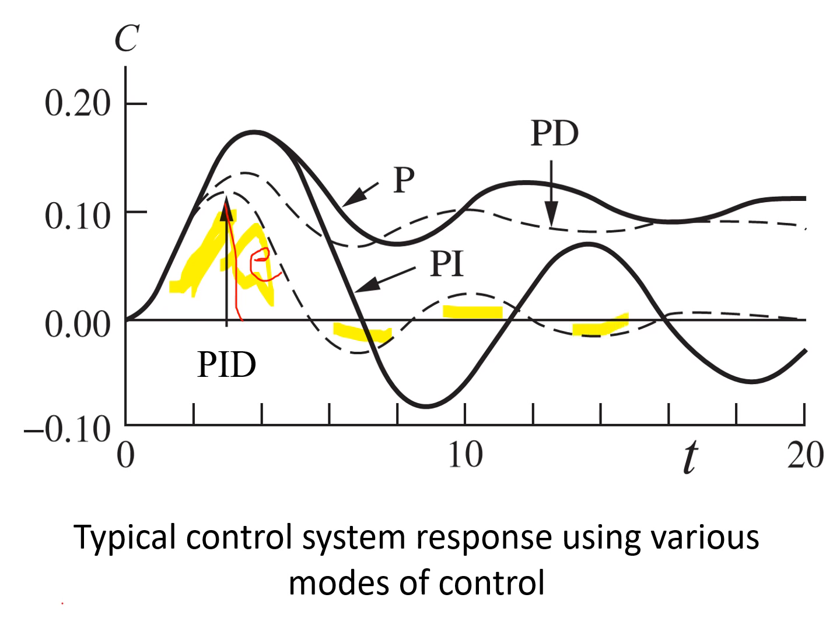That is basically the error for this PID one. That is the error you are calculating. So you are trying to minimize this. By minimizing this, you are minimizing the overshoot and the oscillation to get to the minimum and quickly get to the final value with offset equals to 0. So that's what you're doing using this dynamic criteria covering the whole spectrum.